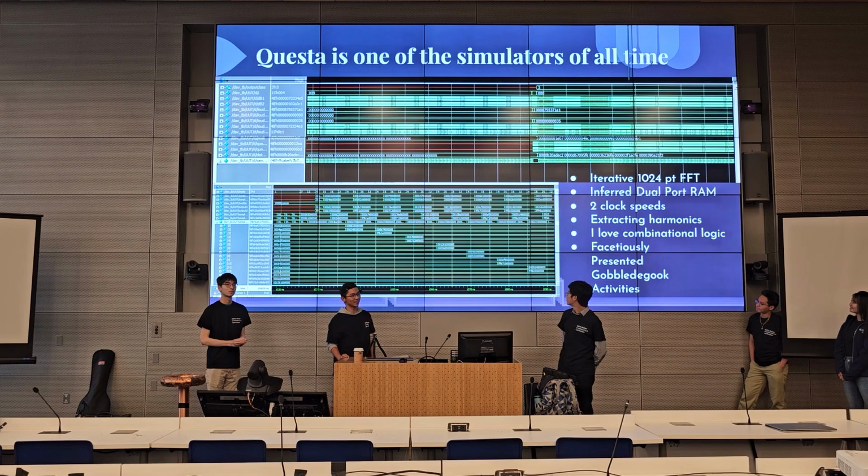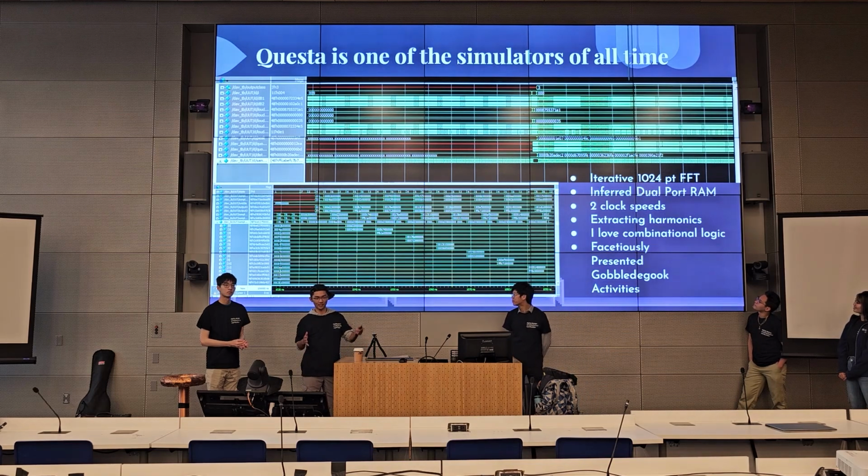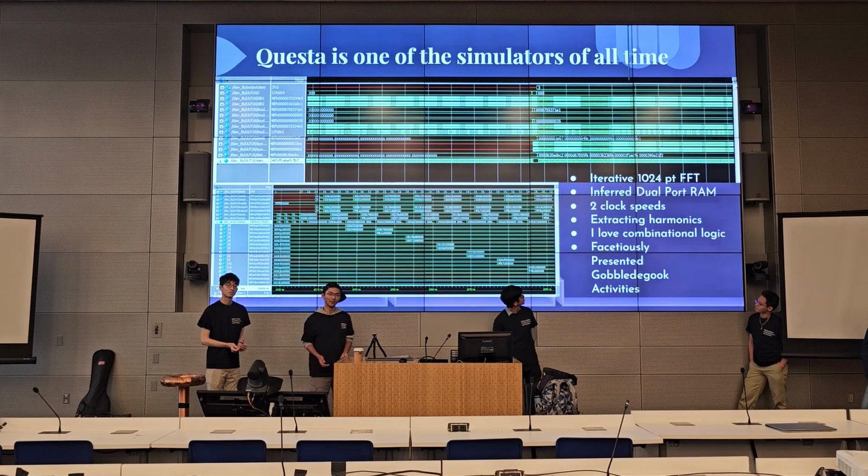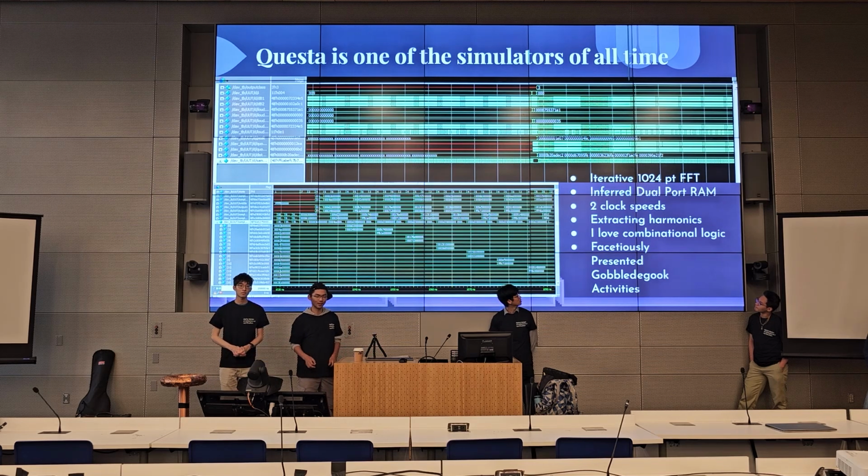And so because of this, we had to shift away from the more intuitive recursive FFT design into an iterative version. And by doing that, we were able to shrink the number of logic elements required to actually implement the system from over 200,000 to just 900. So it actually fits on the device. And then part of doing that included using dual port RAM to actually store values, and there's a not very complicated, but an existing handshake protocol to actually read values in and out of it.